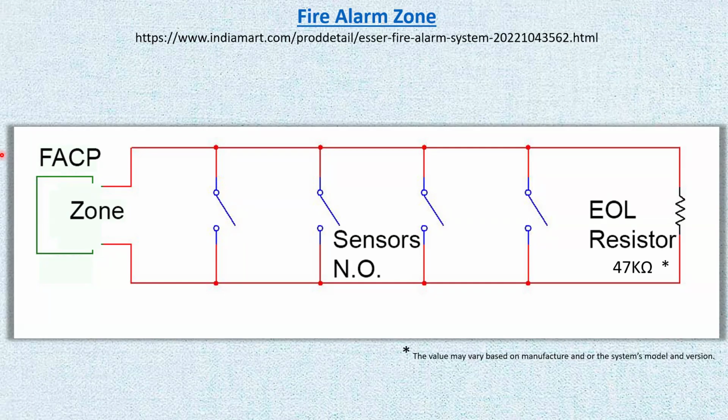So I was receiving all the fire extinguishers, inspecting them for any damage, and depending on the timestamp, some of them had to be emptied and refilled, and the valves and everything else replaced based on the need and the law regulations. And some of them, I think it was every 6 years, had to undergo the pressure test.